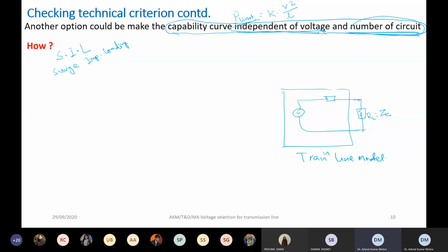It also says that if the transmission line is heavily loaded, the receiving end voltage will be smaller than the sending end voltage. What is the benchmark? I will justify it when discussing conductor selection and going in depth about the Ferranti effect. The benchmark for a lightly loaded or heavily loaded line is the surge impedance loading.